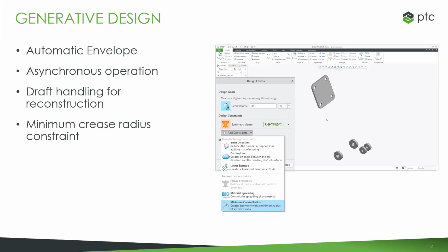Well, I think the main thing I would emphasize is the ability to get manufacturable surfaces out of the optimized model. The older technology, you basically start with a fine mesh and you remove or add elements. So you wind up with a surface that's like sandpaper and can't really be manufactured directly. So that requires subsequent operations to get something practical. But generative design gives you something you can just work off of and go with it.